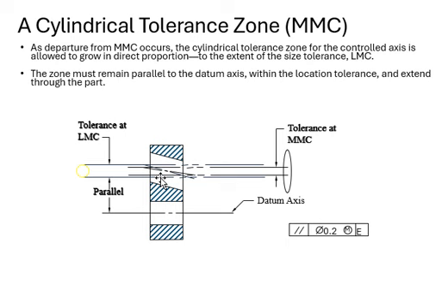You're going to have a little bit of difficulty identifying LMC and MMC. All you have to understand is the least material, I mean here, see the section lines right there? So least material means how much of the part is left because of that hole. If it is max, this material has to be more, so the hole size is smaller.